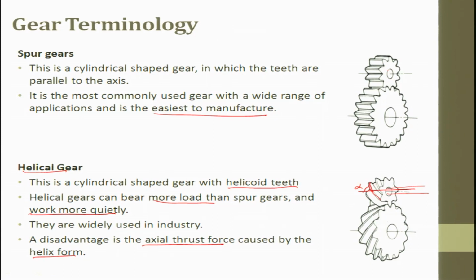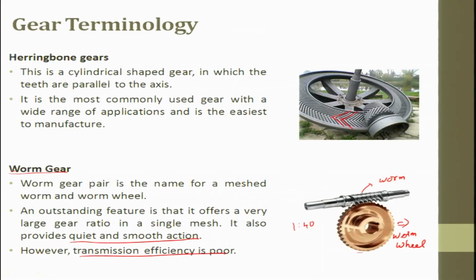In the milling machine, we use an indexing mechanism so that the gear blank indexes at an angle and stops, and then you just use a horizontal milling cutter to cut and generate these teeth.